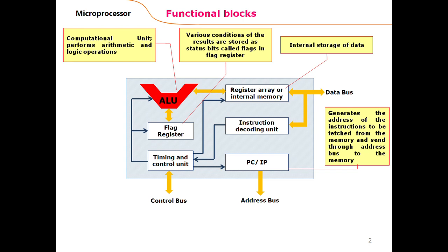So the instruction pointer stores a 16-bit address or the offset address of the instruction that will be executed next. After the current instruction is executed, the microprocessor maintains or stores the address of the next instruction in this register. Together with the code segment, this register provides the physical address or the memory address of the instruction that would be executed next.